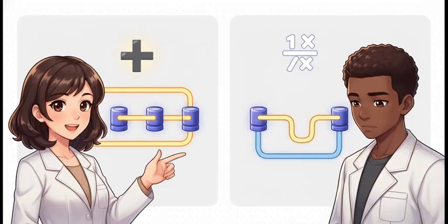So listen up, because this is the crucial point. The math for combining capacitors is the exact inverse of the math for resistors. In parallel, you just add them up. Easy. In series, you have to use that inverse rule. Do not get these mixed up. It's a really common mistake, and it will completely wreck your calculations and your circuit.